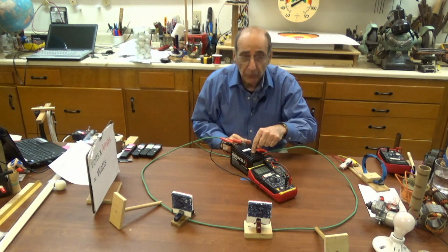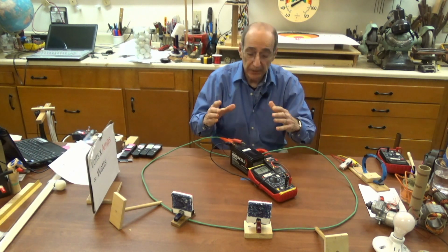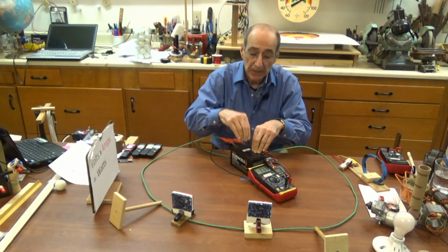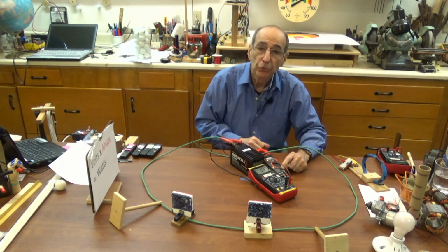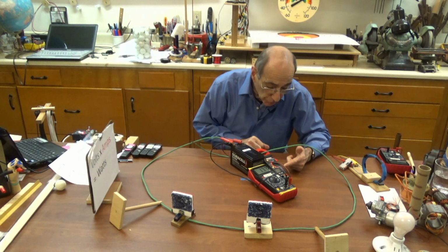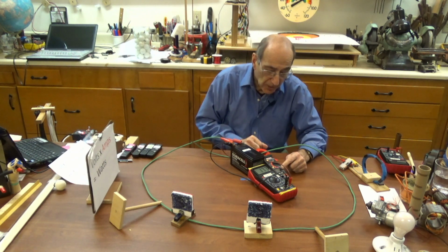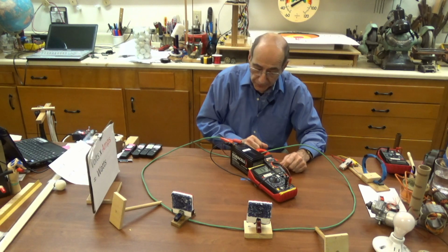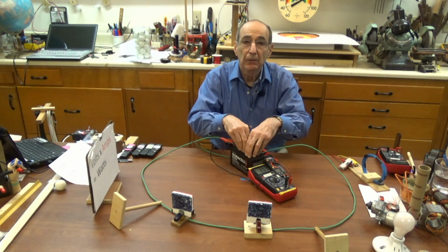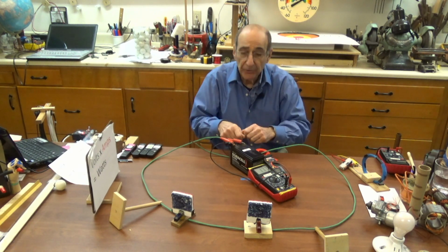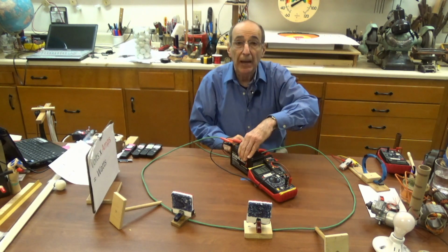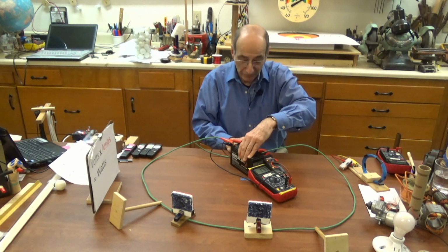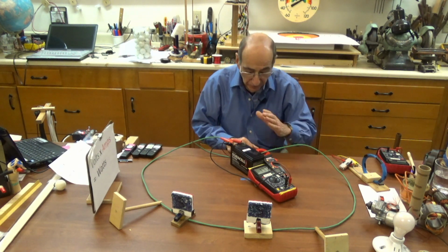At least 10 volts was being dissipated in the battery. 10 times 200 amps, actually more, 215. 10 times that is 2,150 watts dissipated in here. So if I had held that on there for a long time, I would have damaged the battery. Okay? That's why I only keep it on for just a fraction of a second or a second.